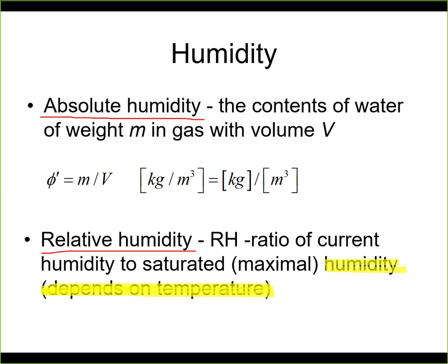We will see that humidity depends also on temperature, and if we have some changes in the temperature, the relative humidity will change as well. You know this from nature. When in the morning outside you see water droplets that have condensed on some trees and grass, for example, this is due to the fact that during the night it was cold, the temperature dropped, and then the relative humidity increased up to 100%, and then the air was not able to hold the water anymore.